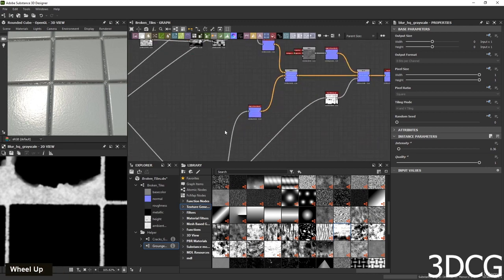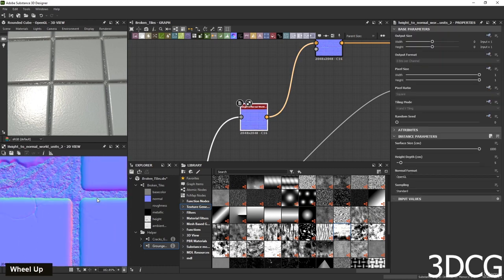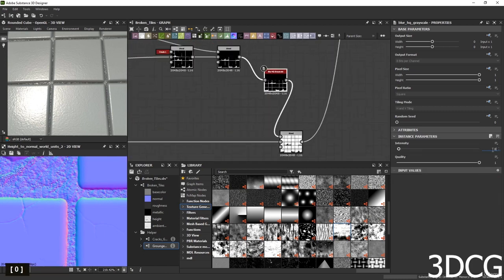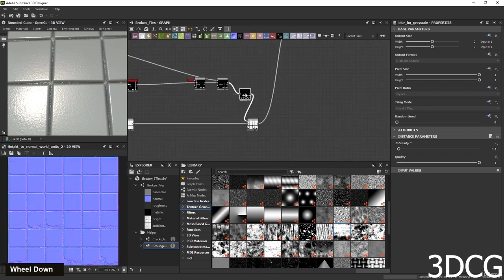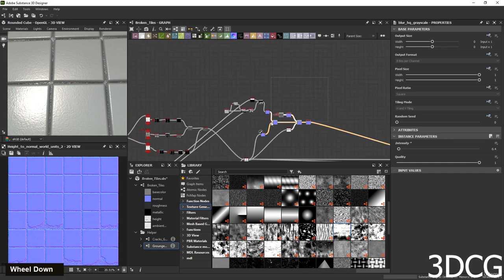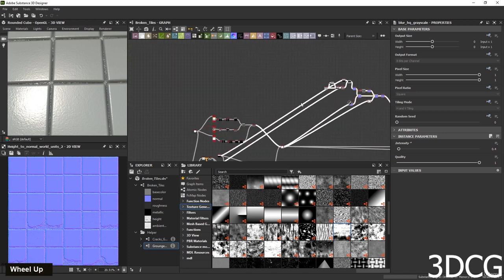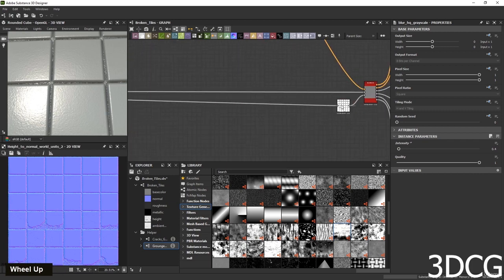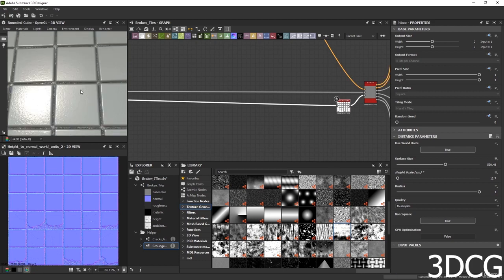Let's go to the normal, and it's smooth now. Maybe a little bit more smooth. 0.4, yeah, it's good. D for dark. And we move the normal section here. All right. Little bit more ambient occlusion for fake shadow in 3D view.